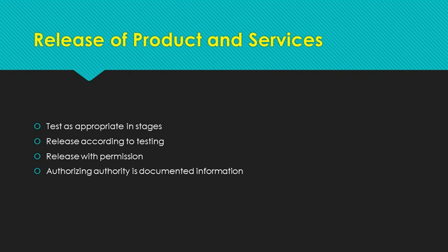In some cases, final testing can take months to complete. The organization must either hold the product for that time period or get permission from a relevant authority or customer. So what would this be? Well, if the product is a concrete foundation, cores will be taken and tested to ensure the foundation can hold the weight of the building. But environmental factors may cause the foundation to cure much more slowly than the test samples. So the idea is to get permission to continue with the construction project as the foundation cures, so that you don't have to shut down for months or even years before continuing.